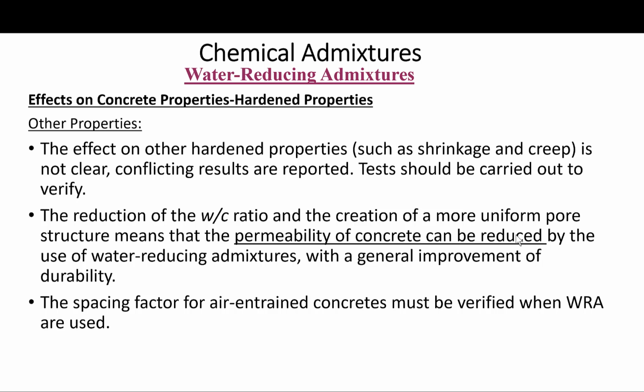Concretes must, of course, be air entrained for frost protection if concrete is to be exposed to freezing temperatures. But in that case, the spacing factor required for good frost resistance is found to be higher than the value required for conventional concretes without water reducing admixtures.